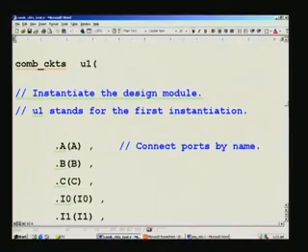So, the connection is nothing but a net or simply call a wire, the physical wire there. So, here it is equivalent to connecting one IC with another. This is U1, you may have another U10, you want to connect a particular pin to U10 from some other pin. So, you have to declare that as a net or a wire, that is the funda in declaring all the outputs here as a wire. Are you clear? The output is defined as wire.